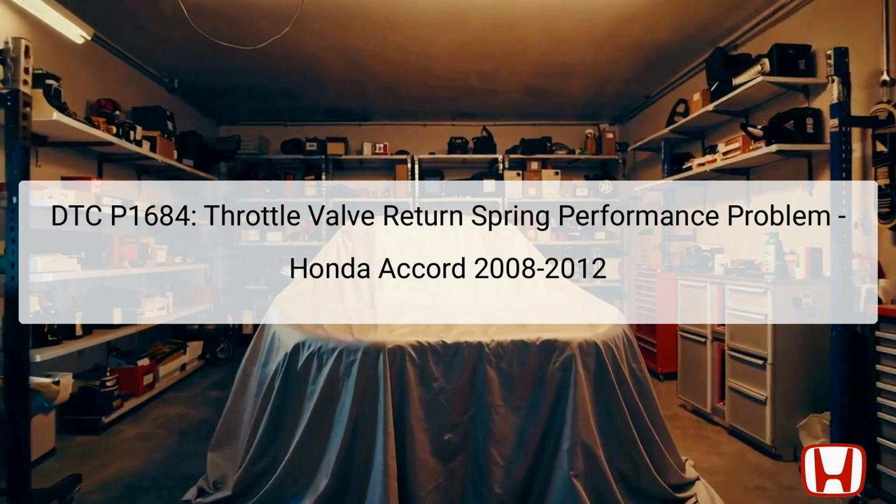The Diagnostic Trouble Code, DTC P1684, refers to a problem with the throttle valve return spring performance in the 2008 to 2012 Honda Accord. This specific issue implies that the throttle valve may not fully return to its closed position when released, which is critical for proper engine function and fuel efficiency.